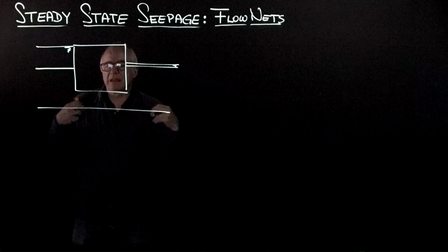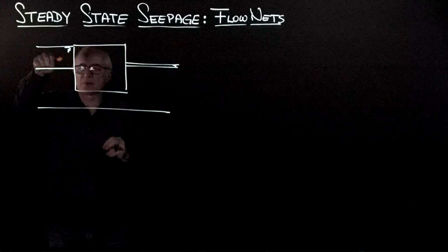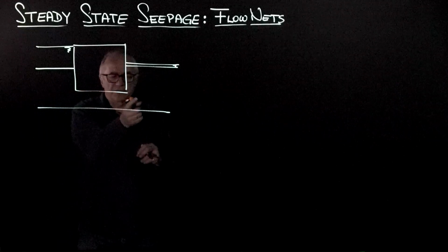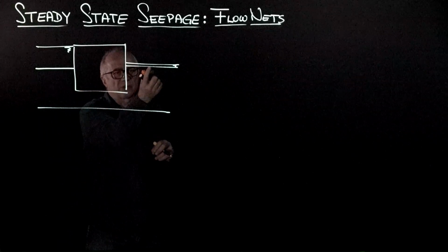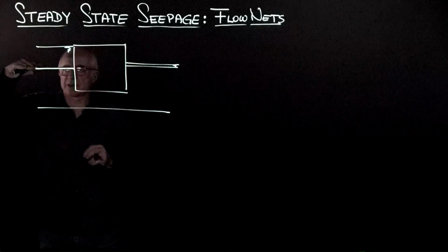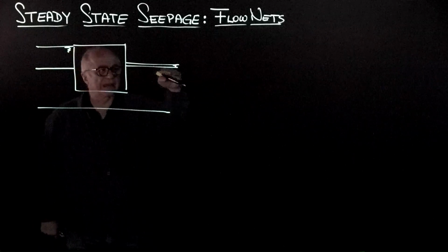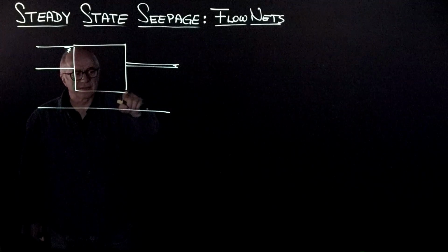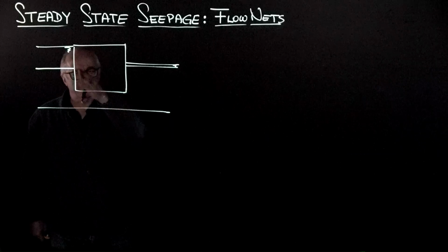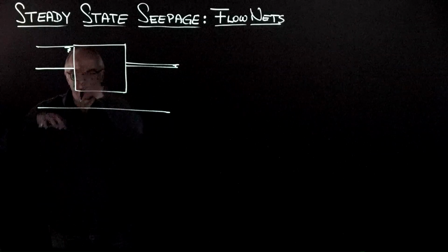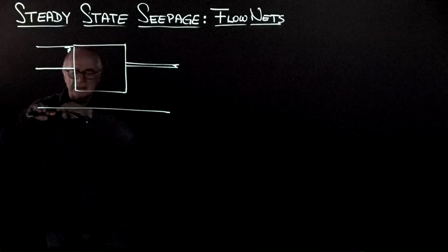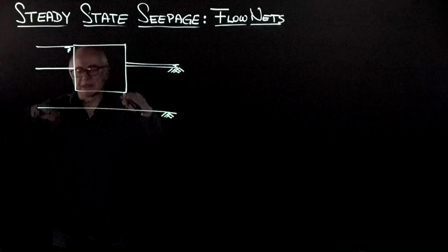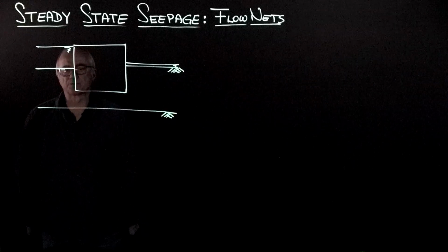If we feel like a water molecule and we put a drop of ink here, we realize that it's going to go down across the basement here and come all the way up. Therefore, this must be my first equipotential. That's my last equipotential. The shortest flow line gives me an idea of the first boundary to the channel where fluid is going to flow, and this is the longest one.